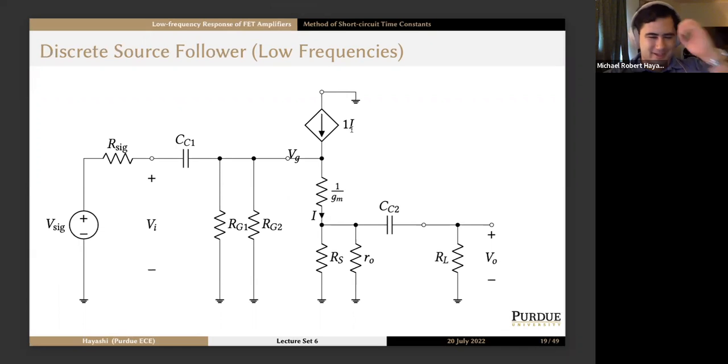Now we did the trick that we did previously, where because RO would be between this 1/gm node right here and the top, which is ground, we just physically picked up the end and reattached it to ground down below so that it was easier to do our analysis. But otherwise, this is a direct application, maybe a second draft of the small signal equivalent circuit that we would try to draw.